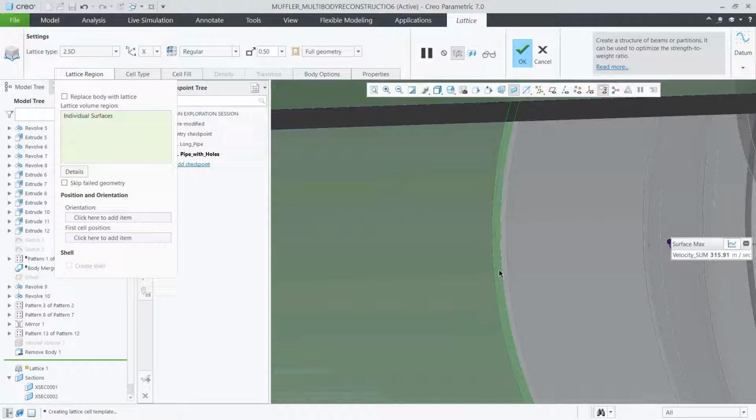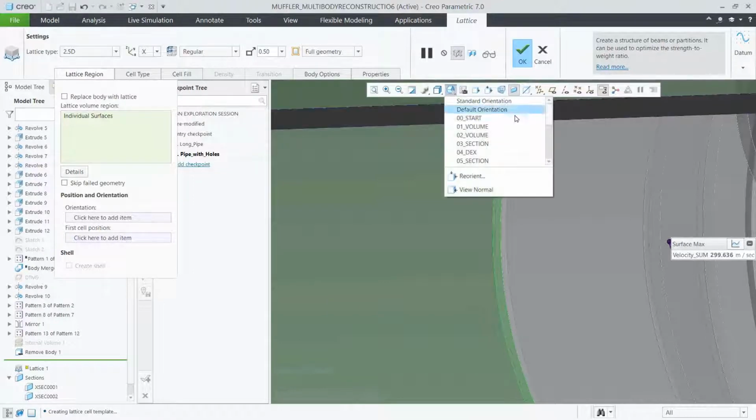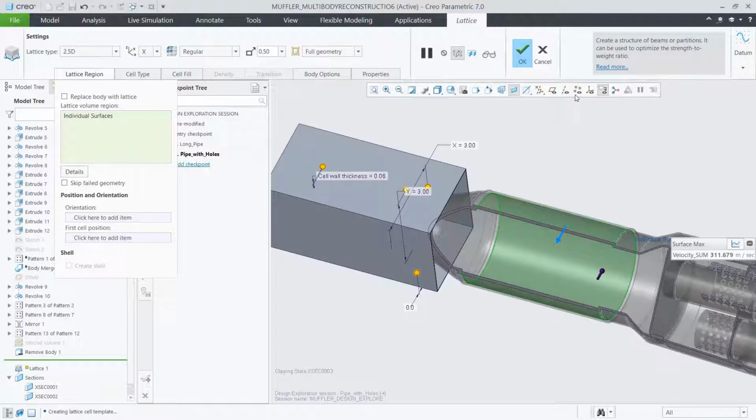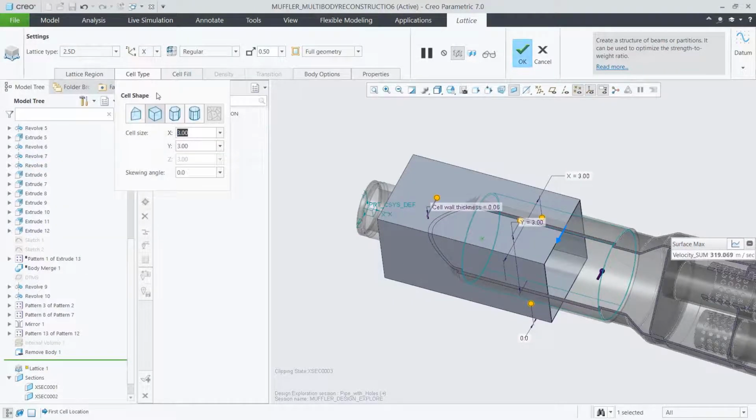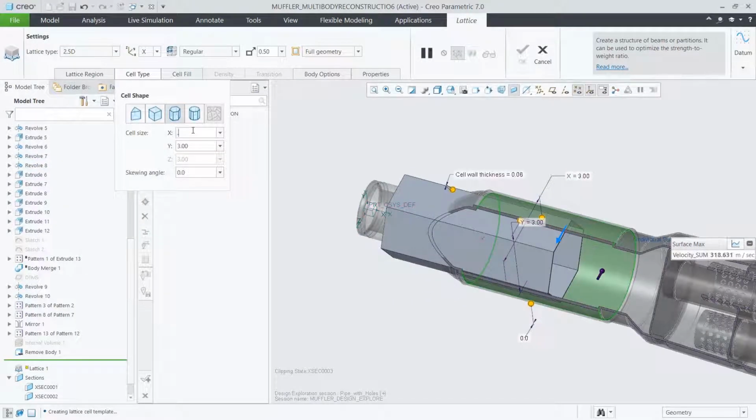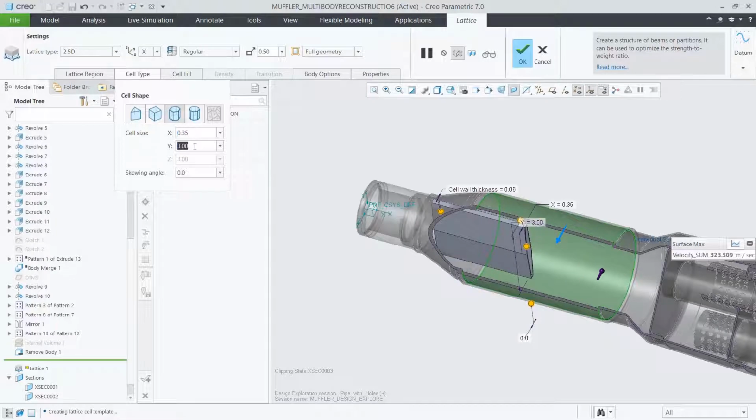And instead of this being just wide open, or in this case drilled holes, let's make it something a little more complex. Let's use the Creo additive manufacturing capability to start here in the center, and I want to put a 2.5D lattice that's more of a hexagon shape. Let's go ahead and set a size.